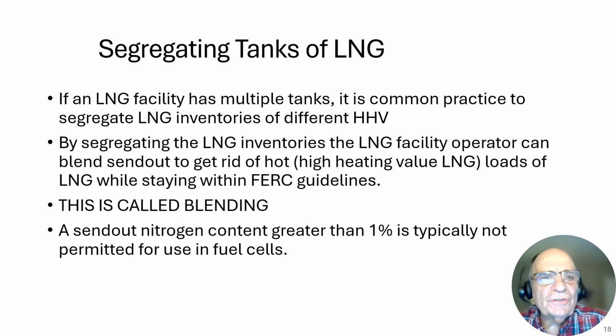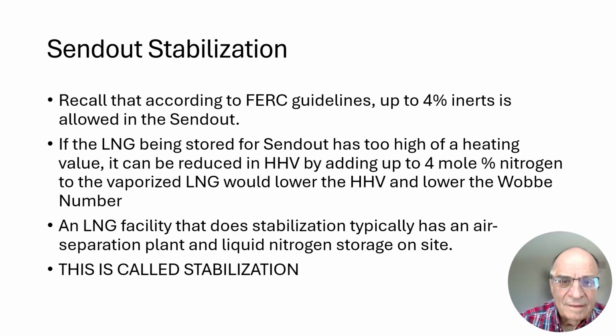If you have the luxury of having multiple tanks, you can segregate inventories between tanks where you have high BTU LNG separate from low BTU LNG. And then when you're called upon to make send out, you can mix the two and thereby meet the FERC requirements of the FERC guidelines. This is called blending.